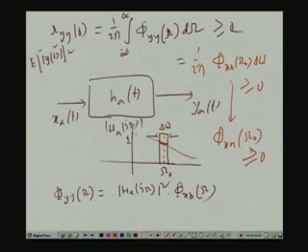But we chose ω0 purely arbitrarily, so this is true for any ω0. If you ask me for Φ_xx(ω) at any ω0, I can design a band pass filter with center frequency at that ω0 and do the proof, and it obviously shows that the power spectral density at that ω0 is greater than or equal to 0. So, it is a non-negative function, is proved.